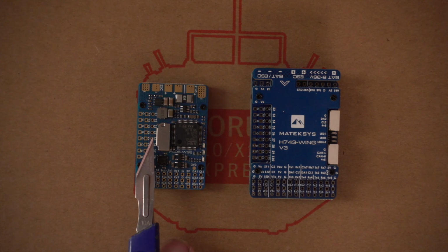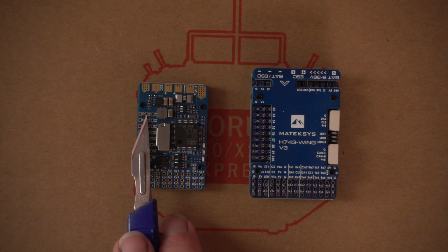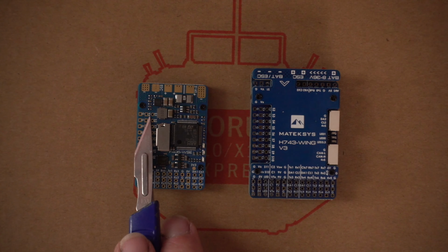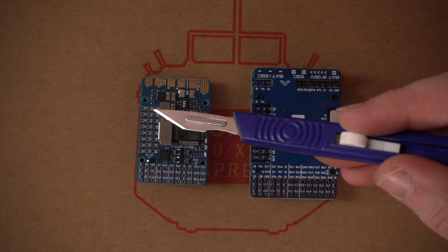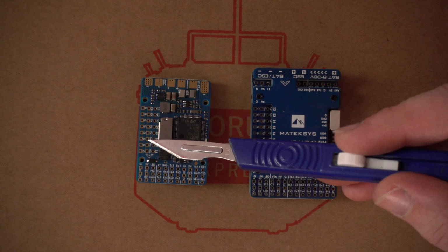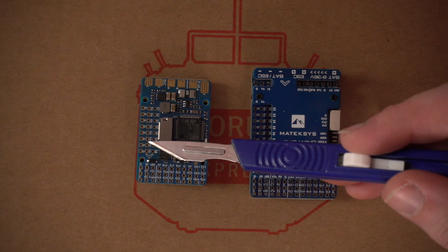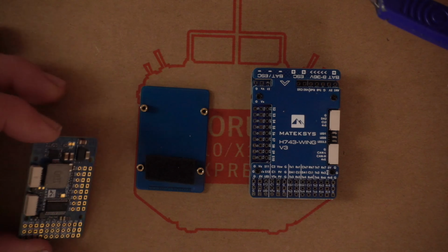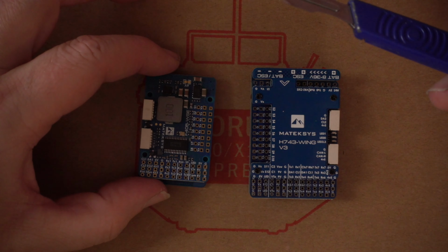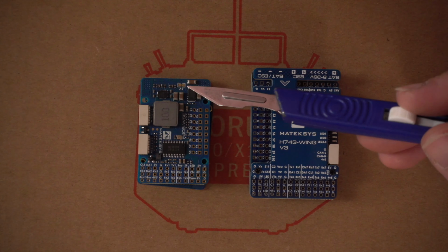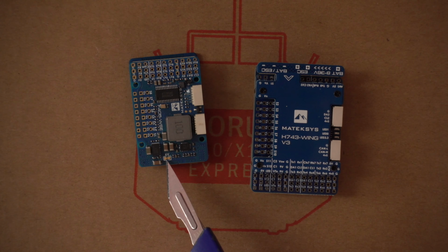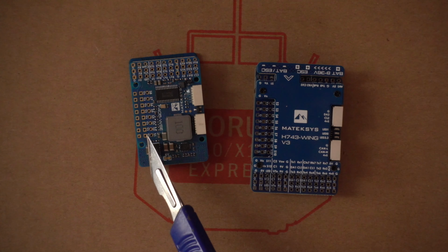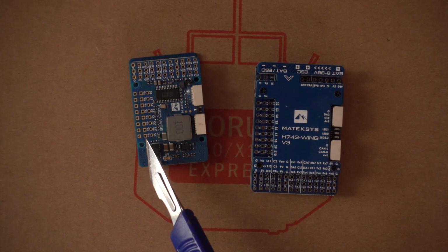So on our servos, the middle pin here is the power in, and you can see it says VX. So with our VX, which is our servo power rail, by default it's running at 5 volts, but if I flip the flight controller over, we should be able to see this pad here. You'll see it says 6 volts. So if we bridge these two pads here, the servo rail will actually become 6 volts.